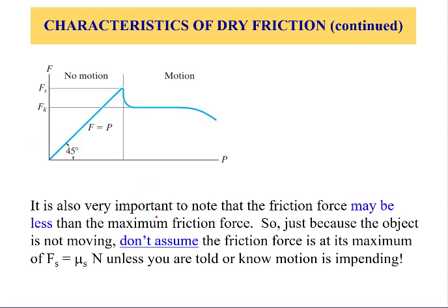It's worth mentioning here that one common mistake is to assume that the friction generated at the contact is equal to mu s N. This is a wrong assumption. In fact, that value is the maximum friction force before the object starts moving. So the friction F could take any value from 0 up to the maximum while the object is not moving.